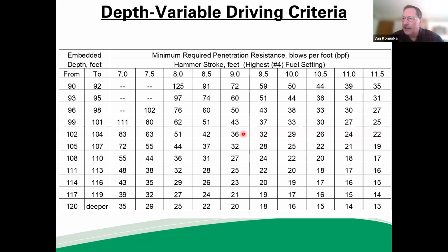I term this an extremely elegant way to take into account both spatial site variability, and by spatial site variability, I mean like in plan view, XY plan view, and the depth variability of the way the setup response comes on a driven pile. Because as you move around a site, the piles will evidence changes in site stratigraphy, in plan variation, in spatial variation, because driven piles are tested piles. And you've developed a design setup profile that varies with depth, and therefore this takes into account that setup coming on with depth.